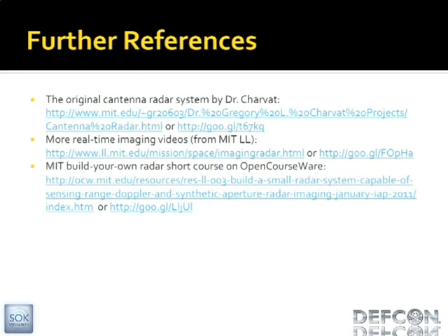He asked if I was looking at software-defined radio systems. I think there would be some benefit to that, certainly for the SAR coherent processing, which would benefit greatly from an FPGA system because it can take a few seconds to process an image like that on the computer. But in this case, the main goal is simplicity and low cost. So if you bring in one of those research boards, like the USRP or something, that's going to add a big chunk of change to your design. But there's definitely a lot of potential there. I would say that's absolutely worth exploring.